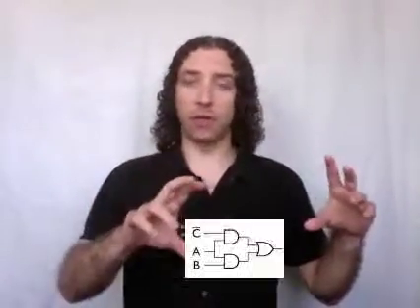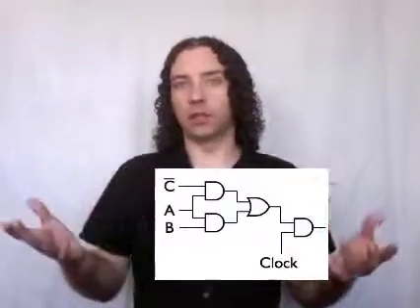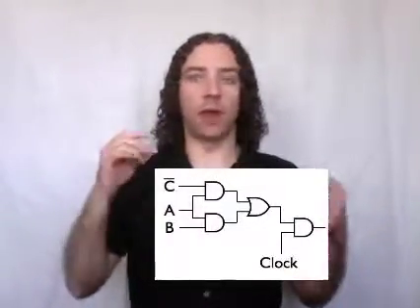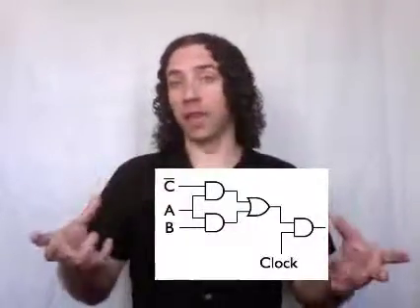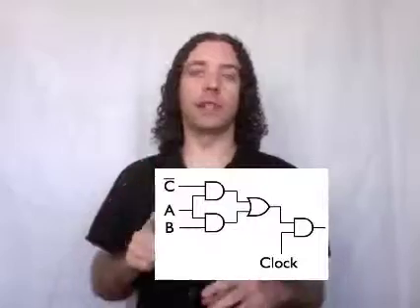So effectively what we're going to do is take the output of this thing and the clock input, and we're just going to AND them together. And the result of that will be the answer that you actually have. And you know that that answer will only be returned because of the AND gate when the clock pulse comes in. So you have a single point where you know the answer will be true or false. Now, how do you determine what kind of clock frequency you can use?